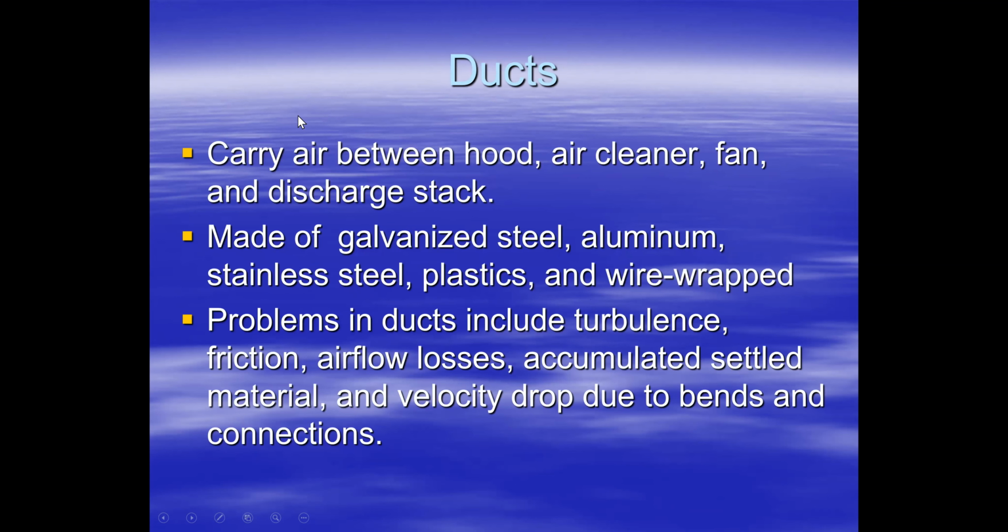Your ducts are there to carry the air between your other components, including a discharge stack. You need a discharge stack and a run of duct before you get to your fan, because otherwise you lose a lot of energy at your fan. If you have turbulence around your fan, it's not going to be able to move that air as well. Your ducts can be made out of a number of different materials. The key factor is making sure the duct material is compatible with the things you expect your ducts to be carrying.